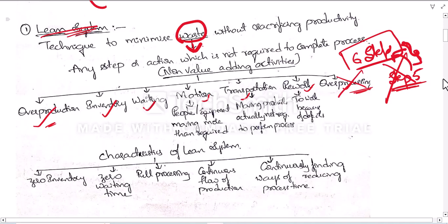And when coming to the inventory, why will inventory be treated as waste? Sometimes we might have purchased bulk raw material which might be outdated or which might have expired, or which might have damage due to long stay in our godowns. So all this will become a waste for us, no? In waiting time, see, nowadays we are following just in time production, but if we check the quality of material after coming into the production line, it is a waste of time.